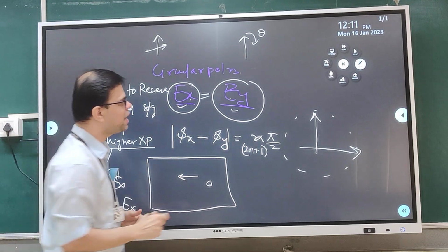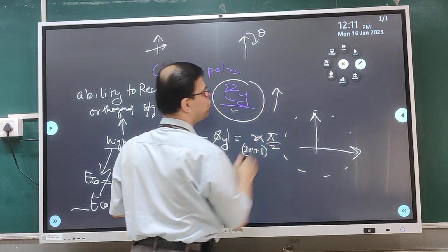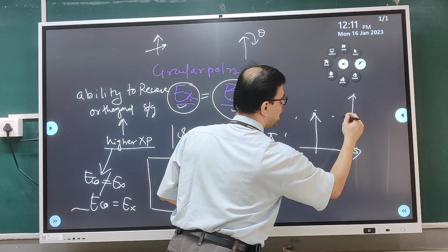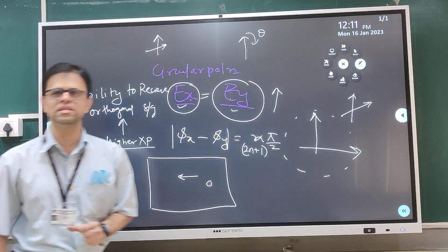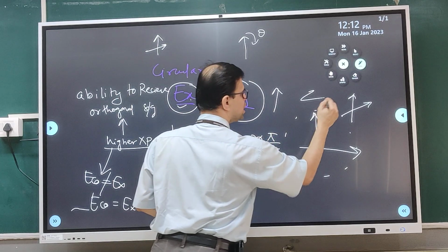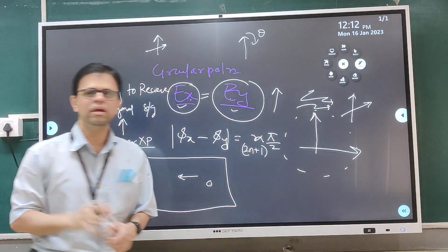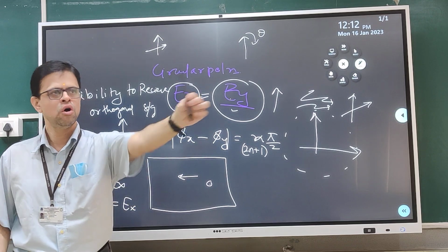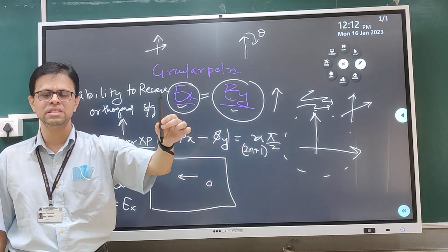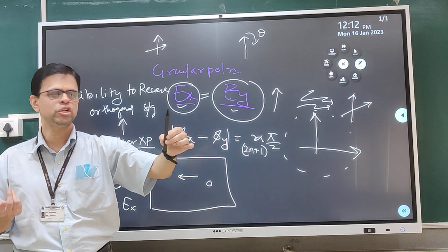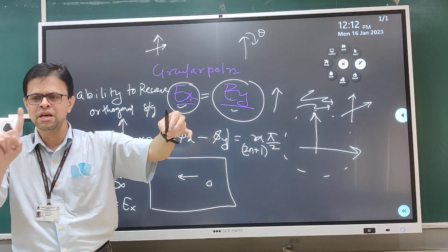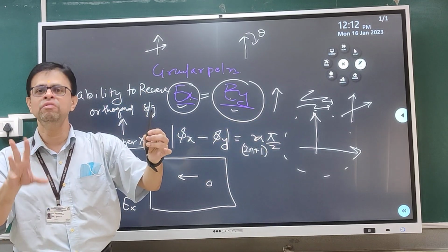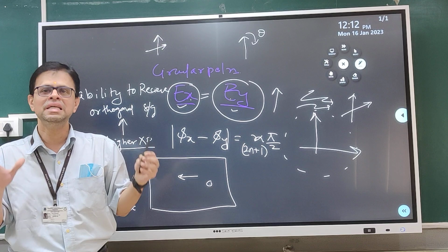But now, if I have a condition, this is my dipole antenna, and this is my receiver antenna. I am using two orthogonal dipoles at the receiver, and through the transmission the signal goes through multipath propagation effects, and the polarization is changed. So at the receiver now, although the transmitter signal is vertically polarized, it has undergone a lot of reflections, so the polarization is something like this. But since I have two dipoles at the receiver side, either of them will receive the signal. I will have a lesser signal loss.